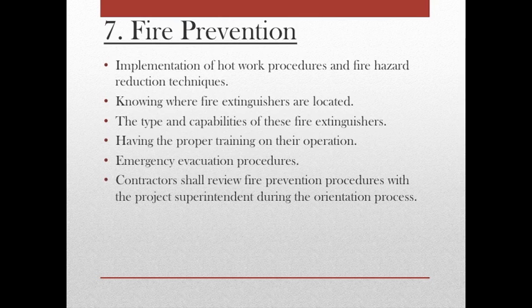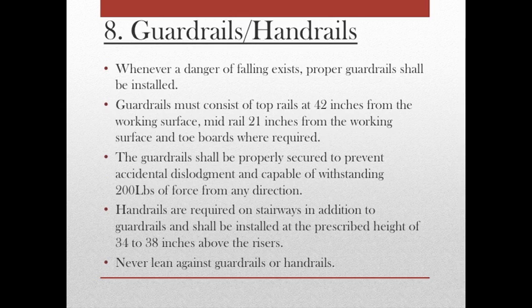Fire prevention. Prevention and protection go hand in hand. There are some basic items that shall be followed, which include implementation of hot work procedures and fire hazard reduction techniques, knowing where fire extinguishers are located, the type and capacities of these fire extinguishers, having the proper training on their operation, and emergency evacuation procedures. Contractors shall review fire prevention procedures with the project superintendent during their operation process.